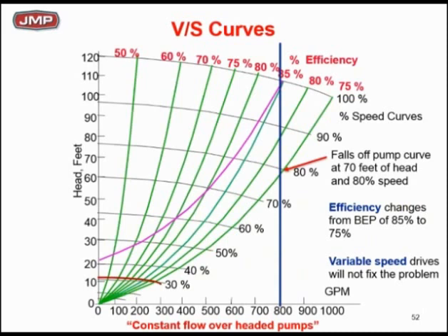And the owners are getting smarter. The owners are saying, how come my pump's throttled and there's a variable speed drive on it? I am getting owners every day asking questions, and they don't know why, but they know that the code says you should have a pump that hasn't been throttled. Minimize throttling losses is the way the code is written.